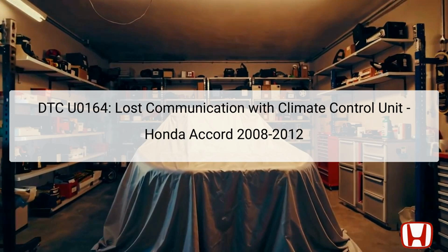These two components work together to ensure optimal passenger comfort by regulating the climate inside the vehicle. The door multiplex control unit is typically located in the driver's side under dash area, while the climate control unit is situated in the center console area, making them relatively close but separated by various wiring harnesses that can sometimes become damaged or disconnected.